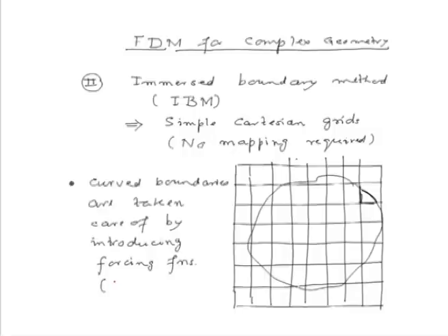Now these forcing functions are very similar to the body force terms. And that is all we have to do. So introduce this term in our governing equation. Now that governing equation could be that of momentum or energy equation.